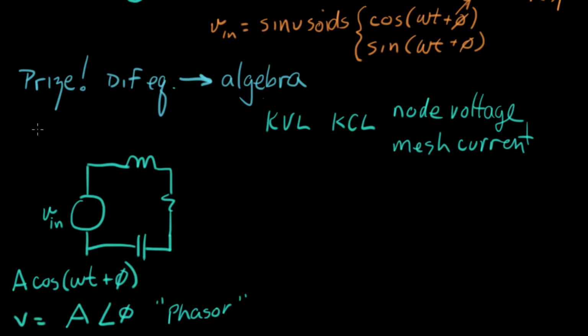So the other thing we're going to learn about is how to transform a circuit, so we can use this sinusoidal steady state analysis. So the inductor gets transformed from L. Instead, we write down SL, where S is that same natural frequency. Whenever we have a resistor, we write down just an R, just like we usually do. And whenever we have a capacitor, we write 1 over SC. And again, this S is the same thing as we had before, the natural frequency. And in a future video, we'll justify why we can make this transformation and what this means.